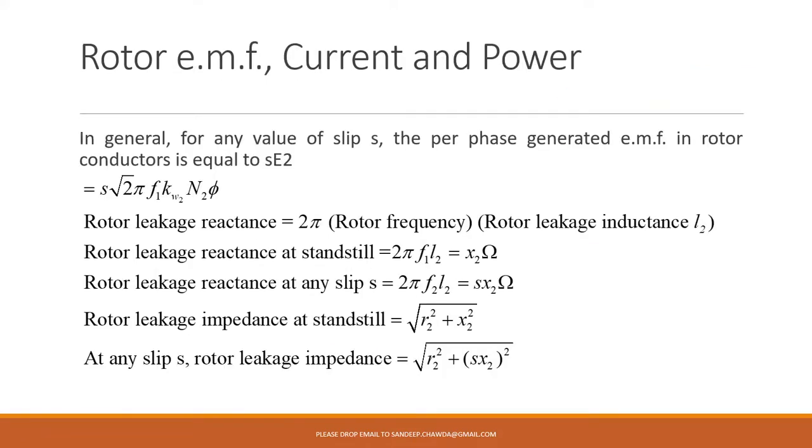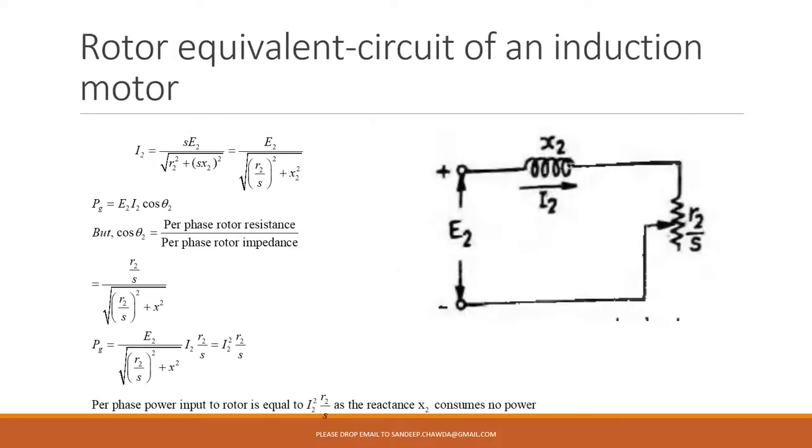Then we talked about rotor EMF. Rotor EMF will consist of slip times supply frequency, or it will have the rotor frequency. So that we have seen, and we came across the expression for rotor current, which is given by this one.